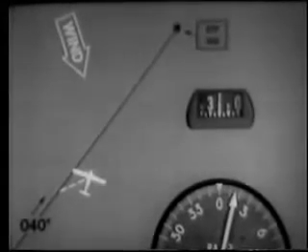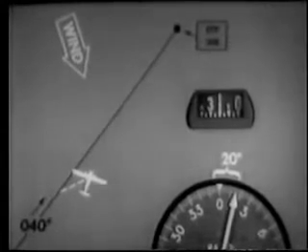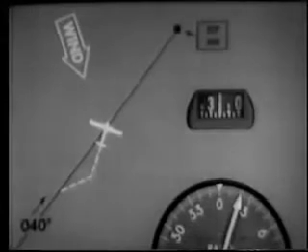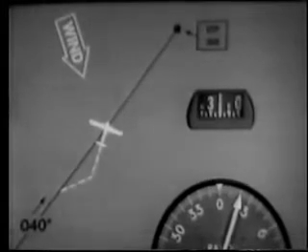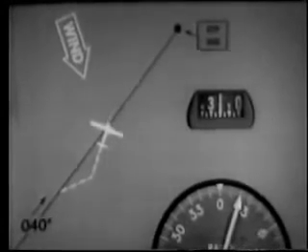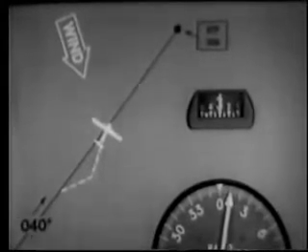Notice that when we turned left 20 degrees, the ADF needle changed 20 degrees, from 355 degrees to 015 degrees. As we progress toward the track, the ADF needle will be deflected further right. We will have reached our track when the ADF needle is 20 degrees right of the nose, since our heading is 20 degrees left of the track. If our 20-degree initial correction returns us to the track, then it would take us past the track if we remained on this heading. However, at this time, we take out half the initial correction, 10 degrees, by turning to a heading of 30 degrees.